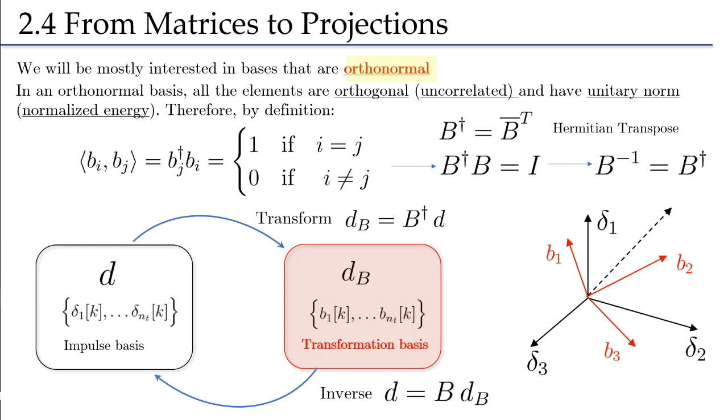So in this particular case, we can move back and forth from the Cartesian to the transformed domain by using simple transposition, which is computationally much easier to handle. Moreover, all orthogonal bases can be seen as rotations, so they preserve the length of the vector from one basis to the other. That is to say, we preserve the energy of the signal as we change the basis.